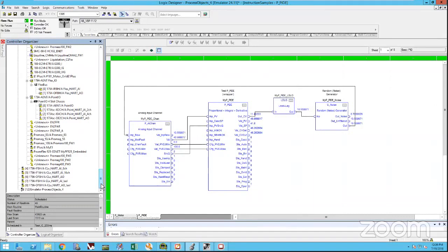Does the new emulator also support Ethernet devices, or just OPC connections? You can do Ethernet devices, but we have a differentiation between plain emulation, where I'm inhibiting, and an Emulate OTS now that does operator training simulator. If you want to bring in an external simulator, it can tie into the emulation box so that you can simulate I/O. That's already out as version 24, and I believe 30, for sure 24. It does allow connections out, but back in the days of soft logic, it only allowed OPC, and none of you want that; you want to allow Ethernet. Exactly.